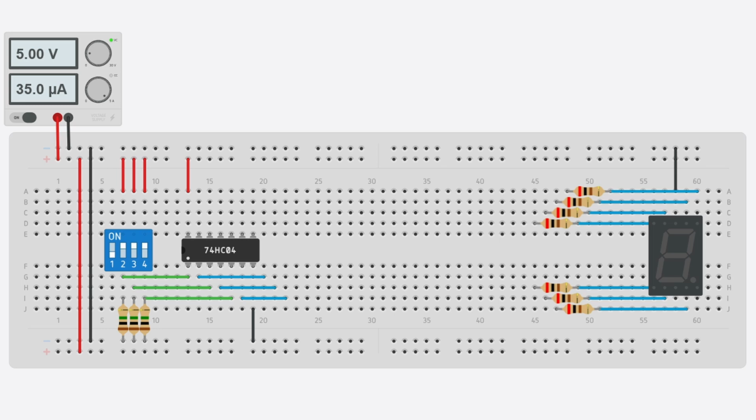So now we'll get to placing the AND and OR ICs onto the board, and we'll create logic circuits for each segment one at a time. On the left, we have the 74HC08, which contains the AND gates, and on the right, we have the 74HC32, which contains the OR gates. You can see that the power and ground connections are the same as we had for the inverter IC, and if you check the datasheets, you'll find that the diagrams are the same as well. They also have the same supply voltage range of 2 to 6 volts, which makes it very easy for us to hook these things up to the same board.